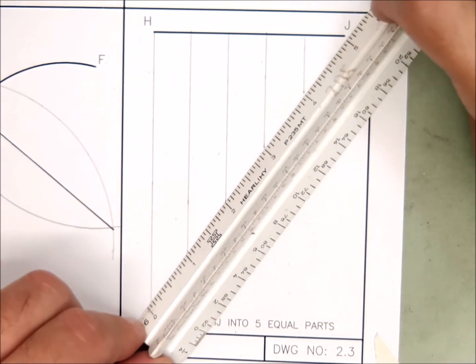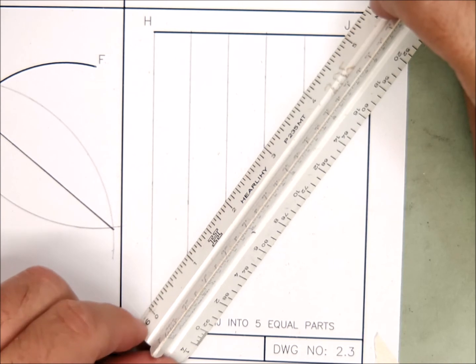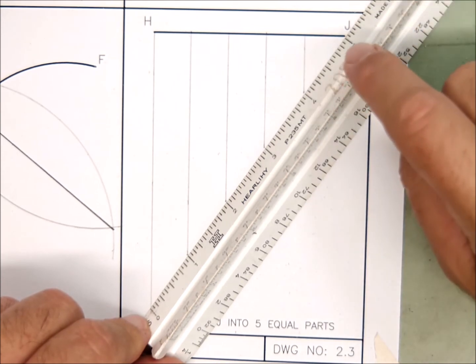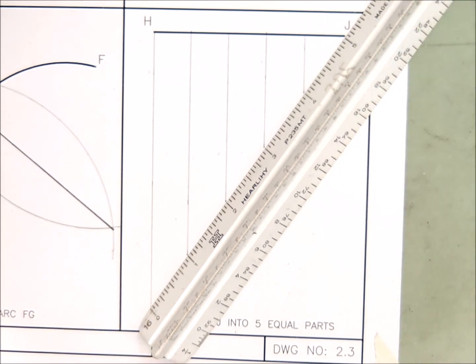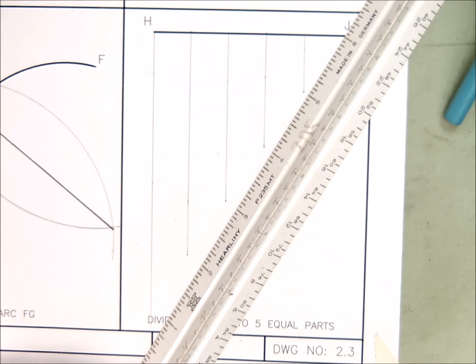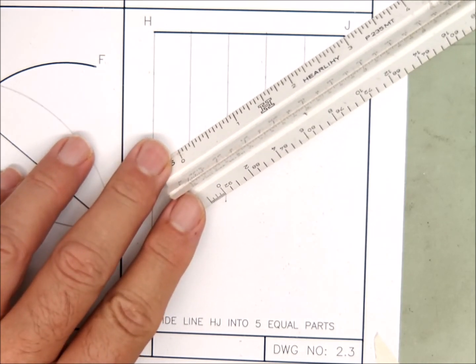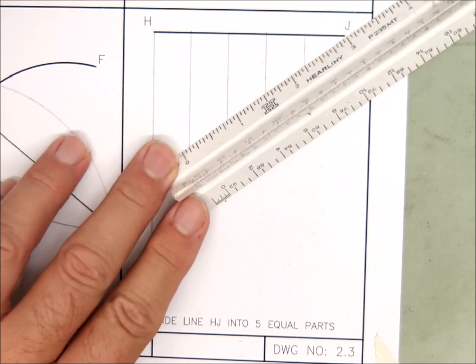When I was setting this up, I had the number 5 at the end of the line, and I had 0 at the end of the vertical line. Do you know why I picked the number 5? If I asked you, why did I pick the number 5 to start from, can you explain why? Well, it's because I want 5 equal parts, right? What if I wanted 6 equal parts? What would I start off with? Well, then I'd have to start off with 6, right? What if I wanted 3 equal parts? Well, then I'd need to start off with 3. Okay? And then the pivot is what's going to give us the divisions as we work our way down.